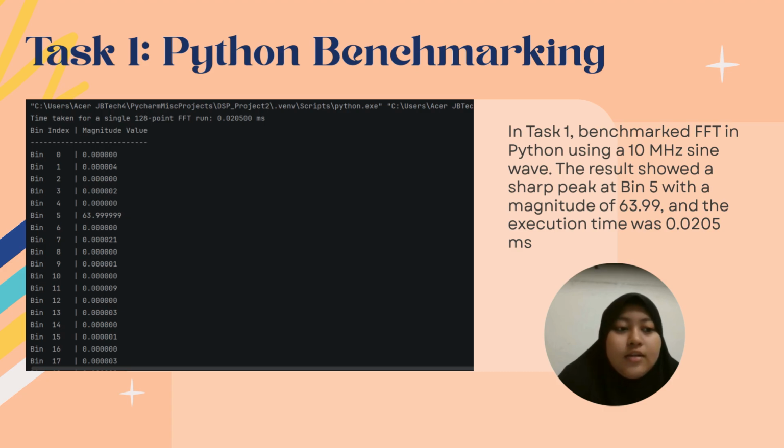In the time domain, the signal looked like a smooth sine wave. When we converted into the frequency domain, we saw a clear peak at bin 5, which matched the expected frequency component. This confirmed that our FFT was working correctly.